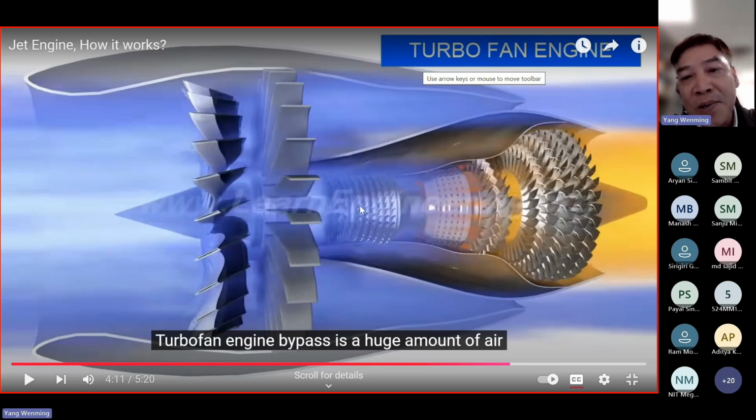So the major component is this multi-stage compressor. From the first part, we know in the high sky the temperature is quite low, can be negative, correct? Can be minus 30 degrees C, minus 40 degrees C. After flowing through this multi-stage compressor, the pressure will be increased and the temperature will also be increased to about 450 degrees C. With this high temperature, the combustion process can be self-sustainable. Otherwise, you have to repeat the ignition process.